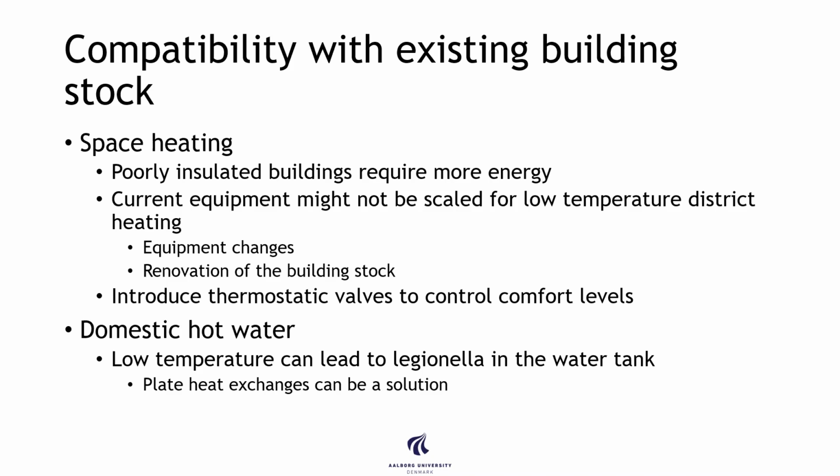One of the risks when you have domestic hot water that you want to supply is that by lowering temperature you can lead to Legionella and bacteria growth in the water tank. So here you want to make sure you have a plate heat exchanger, which can be a solution to having too low a temperature in your hot water supply.